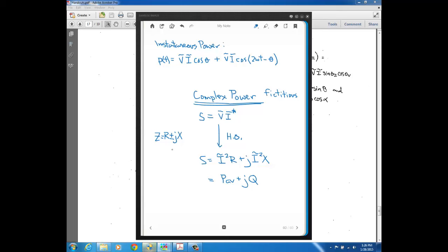So you have the impedance triangle: here's theta Z, here's Z, R is the adjacent side of the right triangle, X is the opposite side. Well, similarly for S, now I didn't show it here, but you could also have a minus Q. That would be Q for a capacitor, where plus Q is for an inductor, just like plus X is inductor, minus X is capacitor.